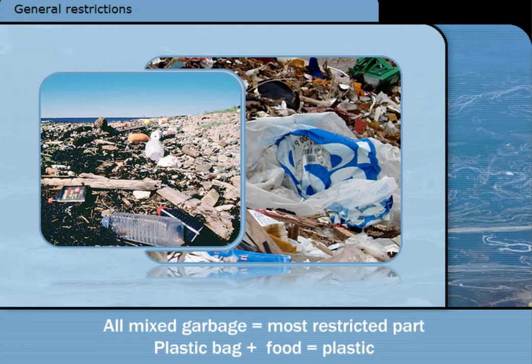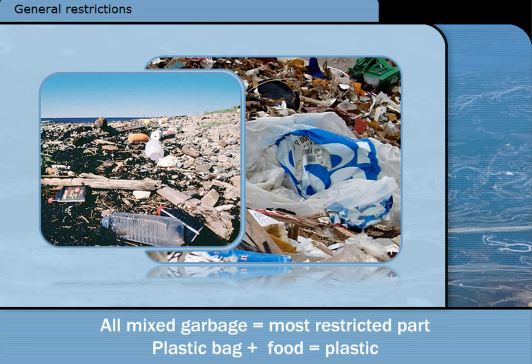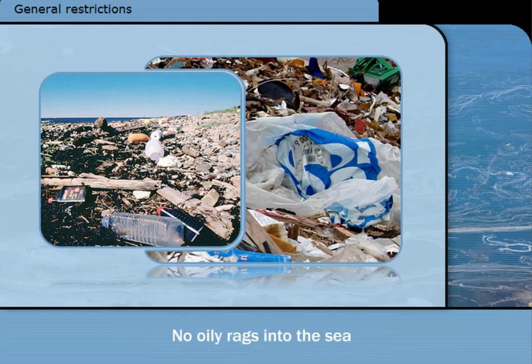Remember that when garbage is mixed, all of it is considered as being made up of the material with the most strict discharge requirements, and it must be disposed of accordingly. All garbage in a plastic bag is therefore considered to be plastic and cannot be discharged into the sea anywhere. MARPOL Annex 1 controls the discharge of oil into the sea. Oily rags must be kept on board until discharged to reception facilities or incinerated.